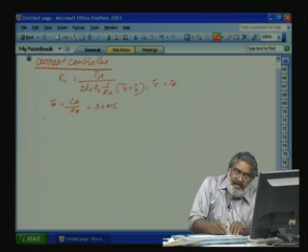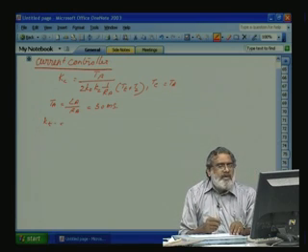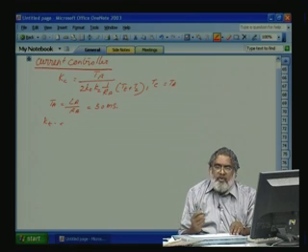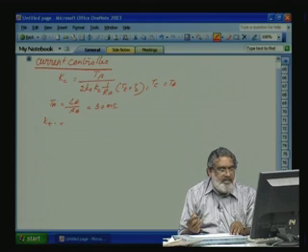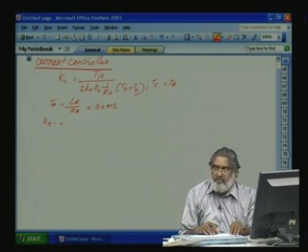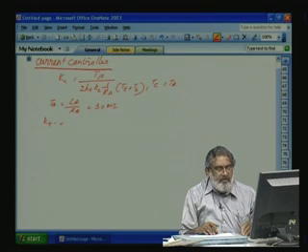Now, what is our converter gain Kt? Let us say we are designing with an analog circuit, so we want to limit the maximum controller output to plus 10 or minus 10. So, when the control voltage input to the converter is 10 volt, we want the maximum rated voltage according to our rating, 460 volts.